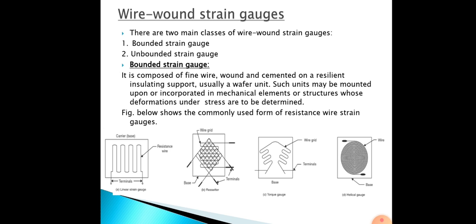The pickup and measuring networks are energized from a similar isolated source. Unbalance originating in the pickup is detected and balanced by a servo-actuated measuring network, providing a reading of strain on a graduated scale. So when displacement takes place between the attached points M and N, there is a movement, either stretching or compressing, and you will get the reading of the strain on the graduated scale. You can see in the diagram that the pointer will be moving, and accordingly you get the reading.